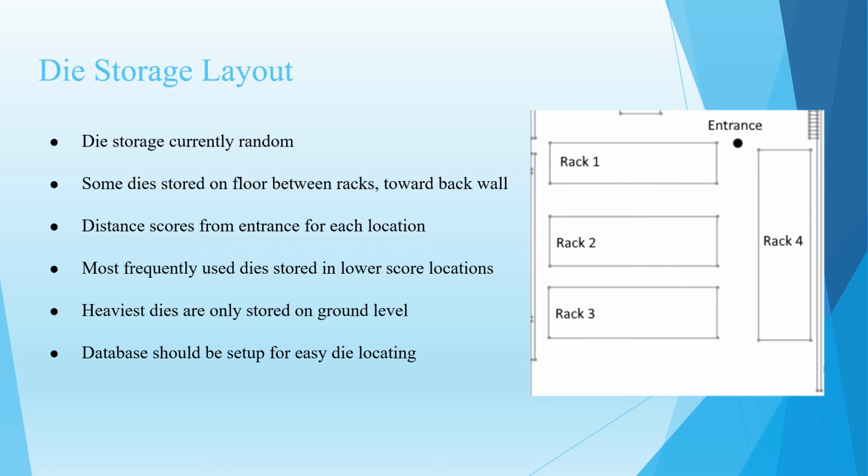In order to improve their die storage, we used a warehouse storage layout algorithm which scores each storage location based on its distance in feet from the entrance of the storage area and pairs the closest locations with the most accessed dies. For safety, we are recommending they only store their largest dies at ground level. In addition, we believe they could greatly benefit from a database that will be used to search for dies.